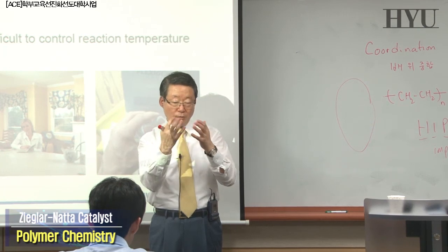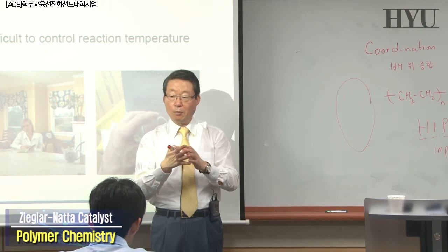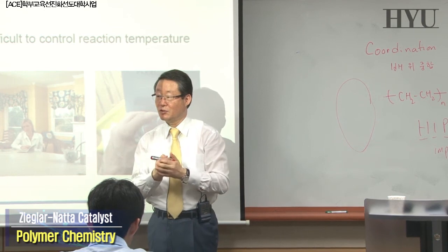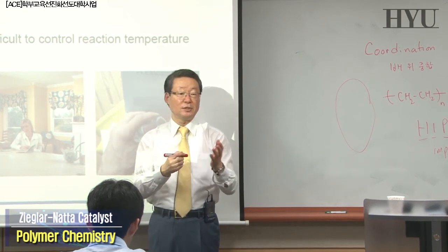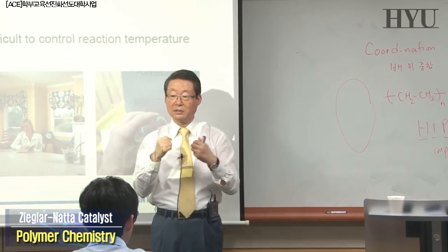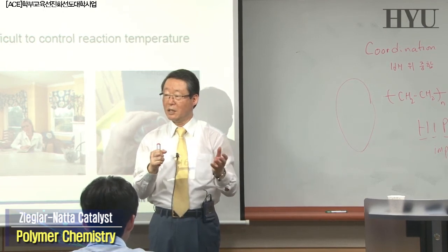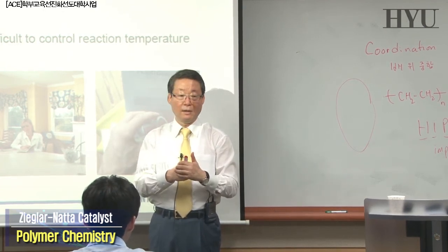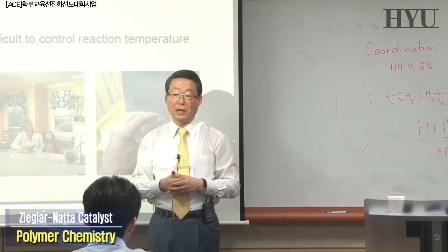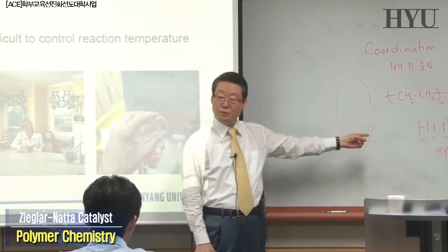you should absorb the impacts, and should add rubbers into your polymer systems to have a high impact strength. How do you get high impact strength? You have to put in something like rubber. Rubber is strong against impact, right? So to be strong against impact, you must add rubber. So polystyrene with a rubbery part, such as a small amount of butadiene, will be a HIPS system.